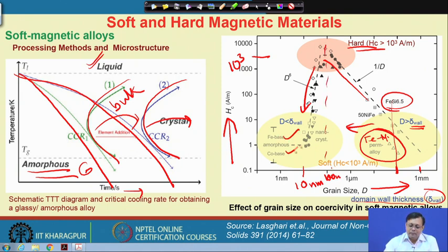So, in case of an amorphous or nanocrystalline magnet, I reach a certain microstructure length scale where the grain size is smaller than the domain wall thickness. It basically says that I can further decrease the coercivity value by producing this kind of amorphous magnet and producing some nanocrystals in the amorphous magnet by controlled annealing treatment, and that will be a better soft magnetic material.